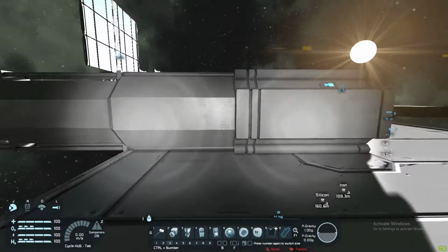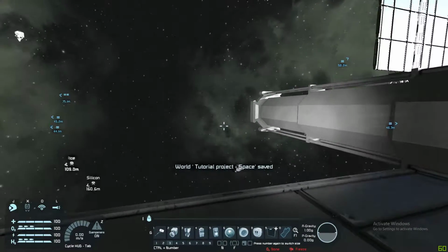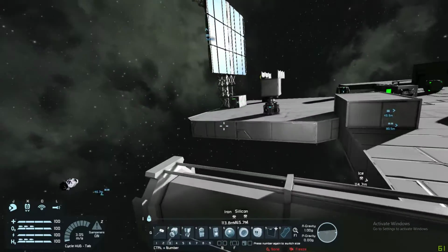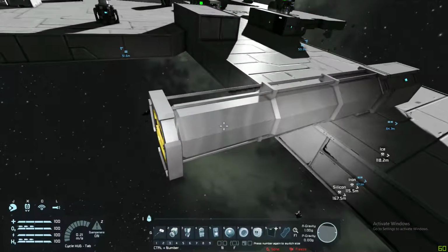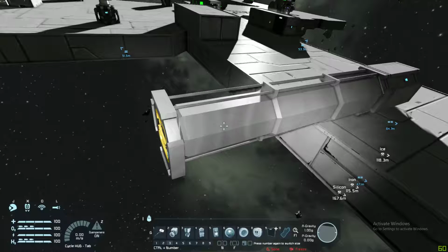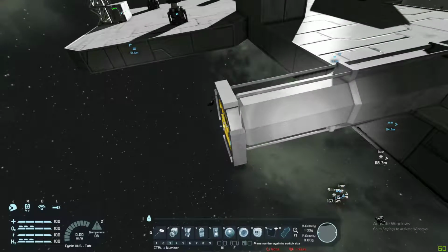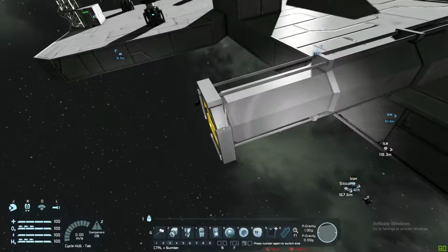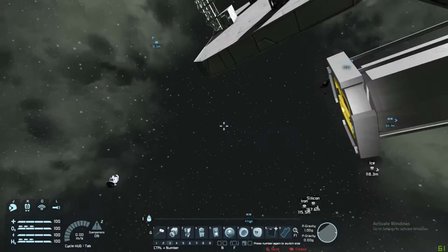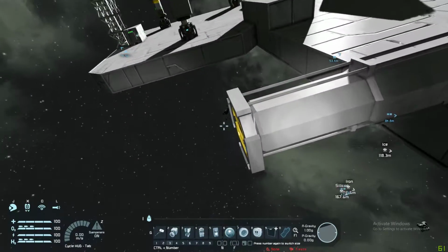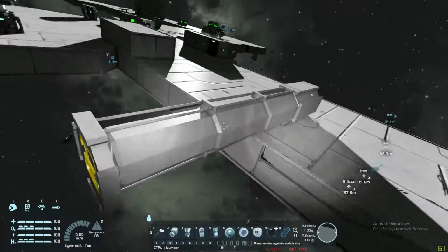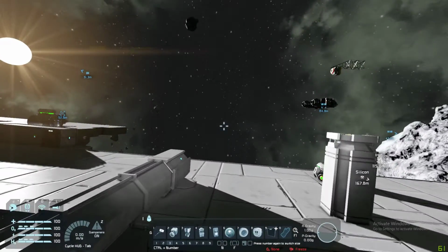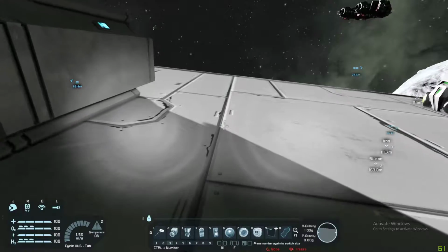Now, if you're using this for just extending out a grid and having it held at a certain distance and it's not going to be moving, using the shared inertia may stabilize your grids. But if you've got moving parts on this end, like a drill head, a rotor, or anything like that, sharing the inertia means that if the drill head hits the rock and starts bouncing, that inertia is going to spread along through your entire grid, and that can cause catastrophic failures.